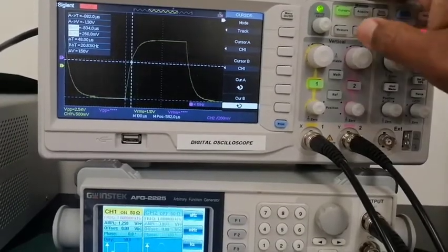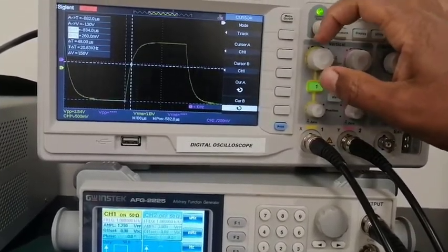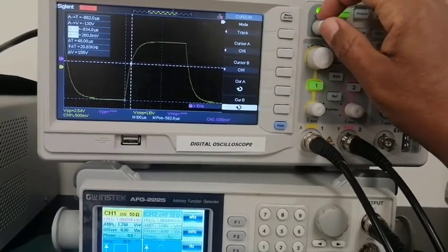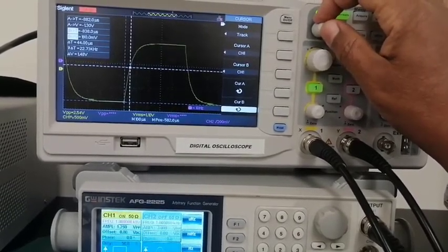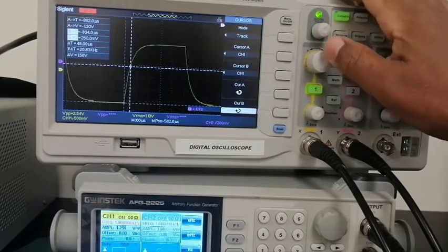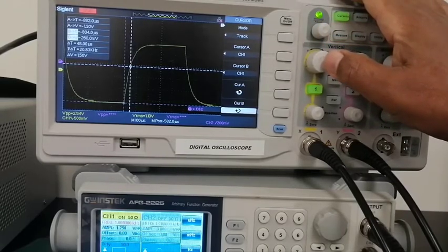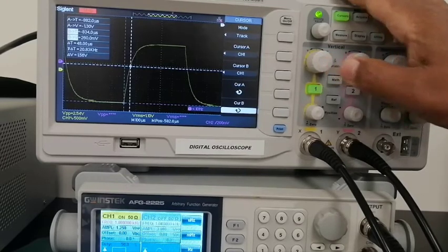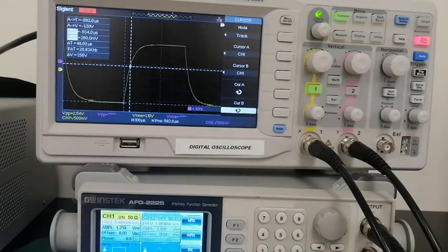Now I am measuring my first time constant. It shows 1.54 at 46, and 1.57 at 47. If I go a little, at 48, between 47 and 46, I got 1.56. So the design is confirmed, similar to the calculation.